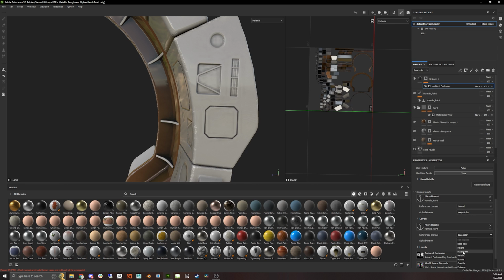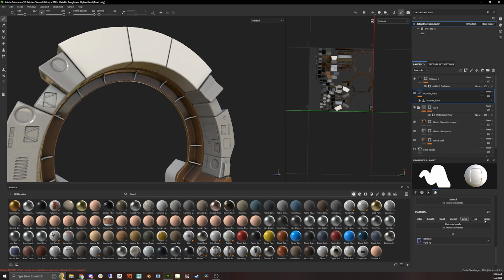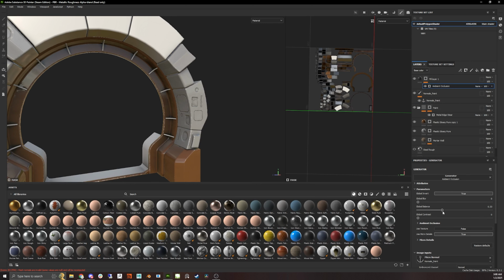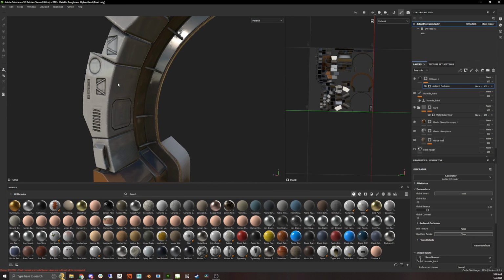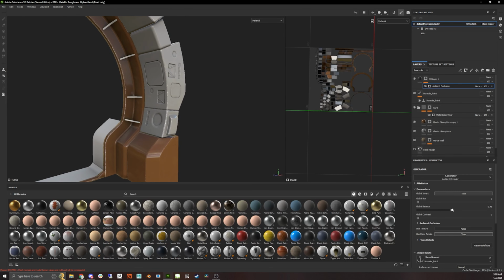Now, even though we don't have a height channel, we're going to change this anyway to height, just for brevity's sake, in case we ever added a height. If we ever wanted to come back here in our normals and add a height anyway, we want to change that. So if we go into our ambient occlusion again and start pulling this down, you can see immediately the difference: all of these different sections now are taking in that element. And then we can even keep using it, so that if we raise it back up, we just want a little bit of darkness in all of our areas.